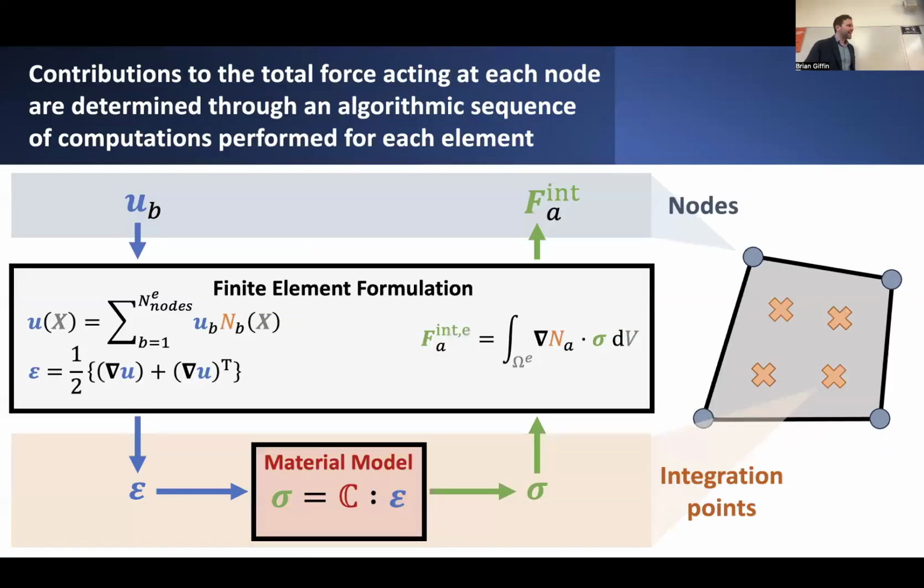Before we dive into that, I want to refresh your memory on some of the things we talked about in the last lecture, specifically how we came up with these relationships between nodal forces and quantities defined at the nodes, explaining how each individual node might discretely displace in different directions independent of one another. And we took that description of displacements at the nodes, and through our formulation of the finite element method, we were able to relate these discrete values of displacement at the nodes to the corresponding values of strain at different interior points within the element. So that was a crucial distinction.